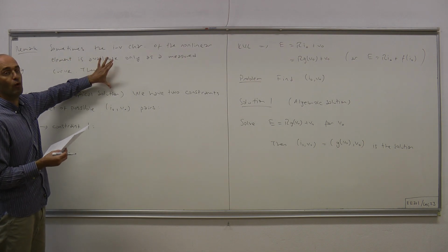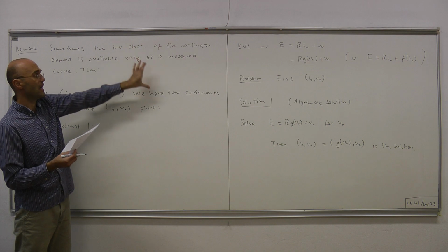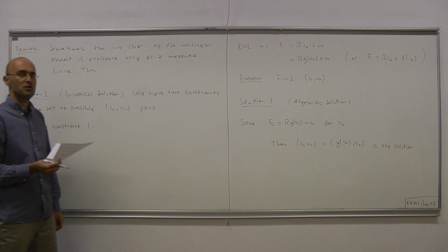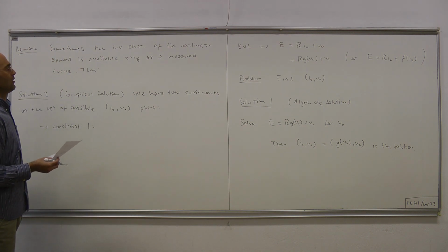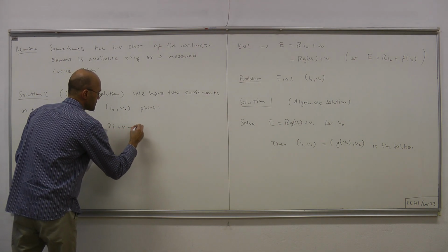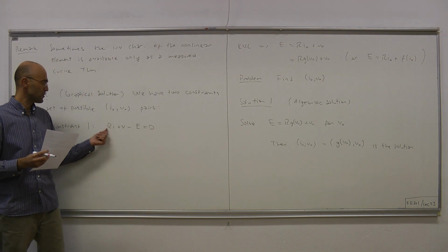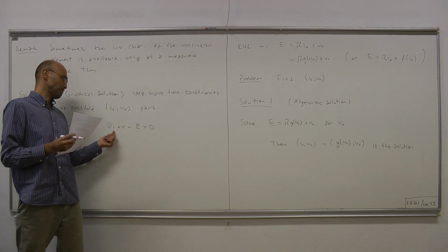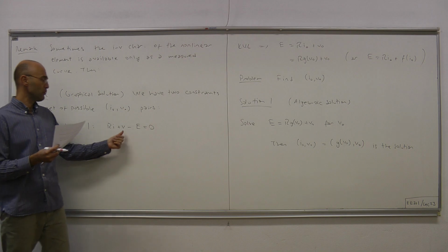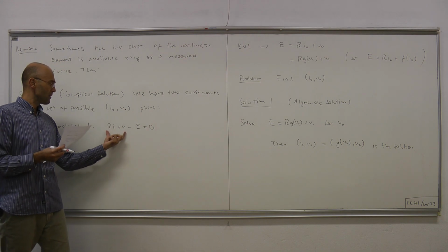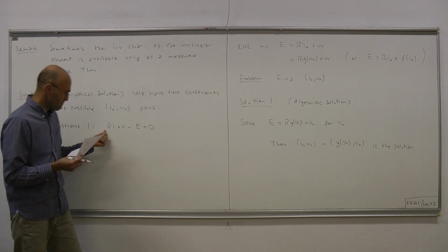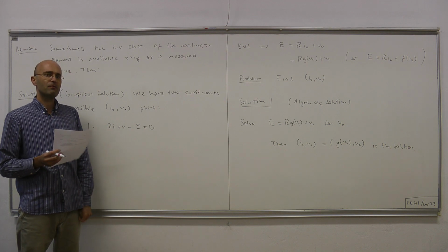Remember that we have the voltage source and linear resistor and our nonlinear resistor. They all make a loop. So by KVL and the terminal equation of the resistor, we have Ri plus V minus E equals 0. Okay, R times I is the voltage of the linear resistor plus voltage of the nonlinear resistor, and that sum must equal the voltage provided by the voltage source. Therefore we have Ri plus V minus E equals 0.